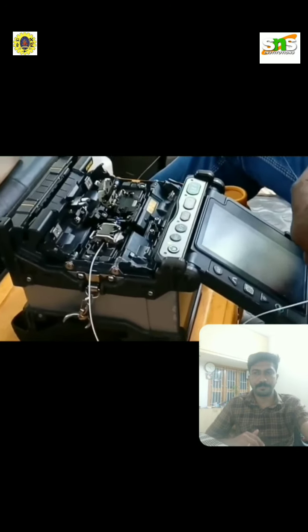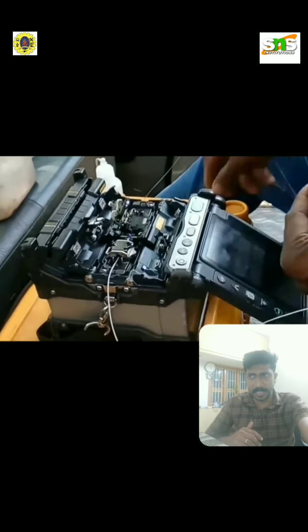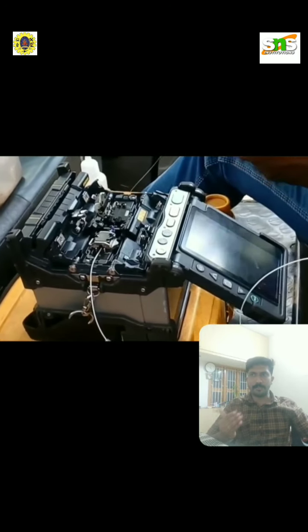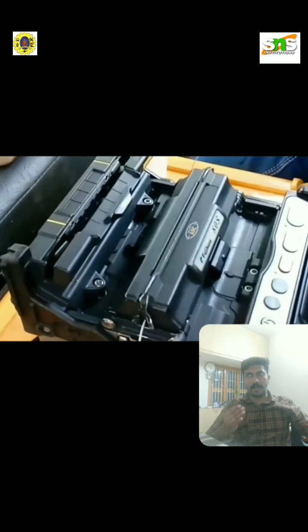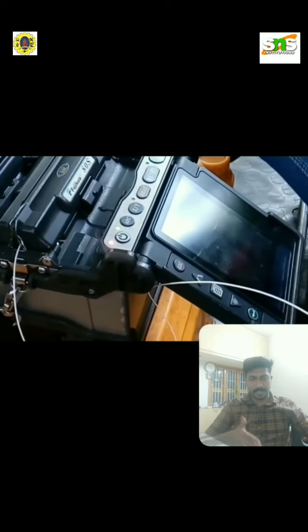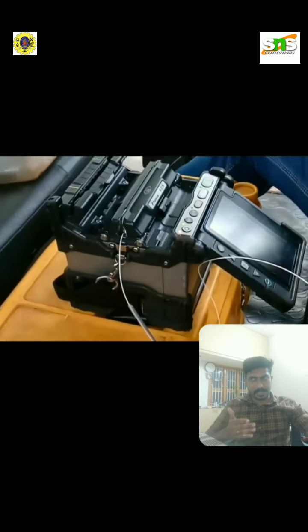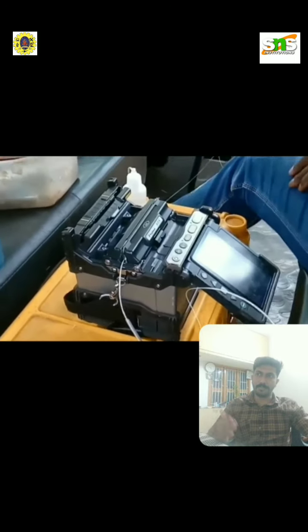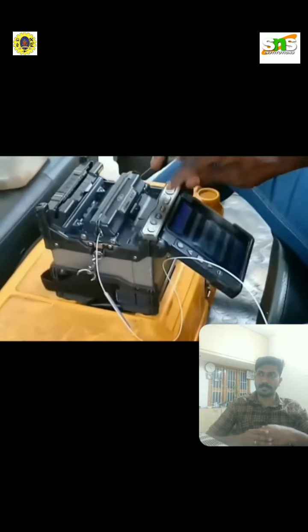The third step is to fuse the fiber. When fusing the fiber, there are two important steps: aligning and melting. First, align the ends of the fiber within the fiber optic splicer. Once proper alignment is achieved, an electric arc melts the fibers to permanently weld the two fiber ends together.